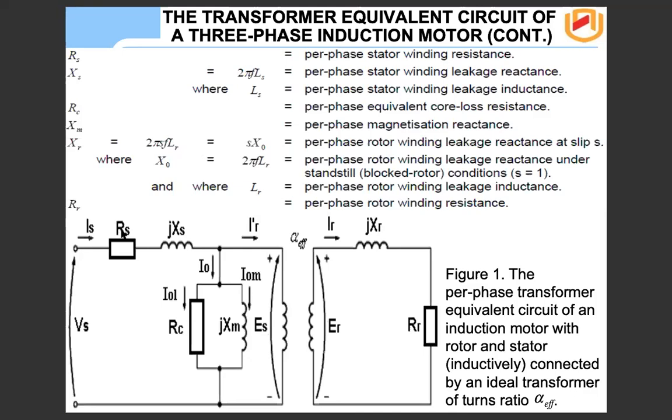Now S represents stator and R represents rotor. It's simple. This is stator resistance, this is stator reactance, and this is the core loss resistance. Remember we still have laminations of those core materials. You saw in the video where we stacked some laminations, so there are still core losses. Remember, these are due to eddy currents.